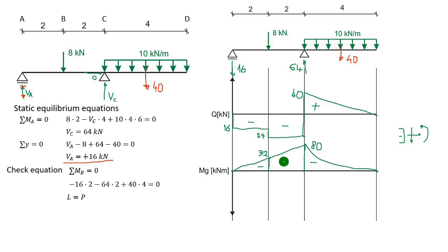Well, I'll tell you, I thought it would look worse. It definitely doesn't look beautiful, but I think you can see something. Of course, the slope of this linear graph changes here. There is a kind of bend, just like that 8; you could say this graph bends here at the moments. And this is what the moment graph and the shear force graph look like without writing the functions. Of course, with commentary it took a bit longer, but in reality, this graph could have been drawn in 3 minutes. So the method is nice.